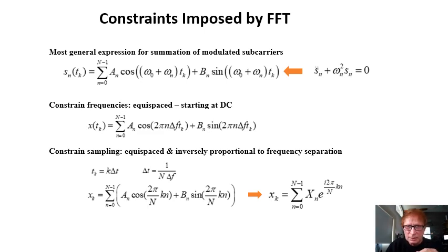right. The frequency offset term, omega sub 0, in this model will allow the use of a direct RF sampled mechanization with no mixer for down conversion. This will be discussed further as we get into the new algorithm.